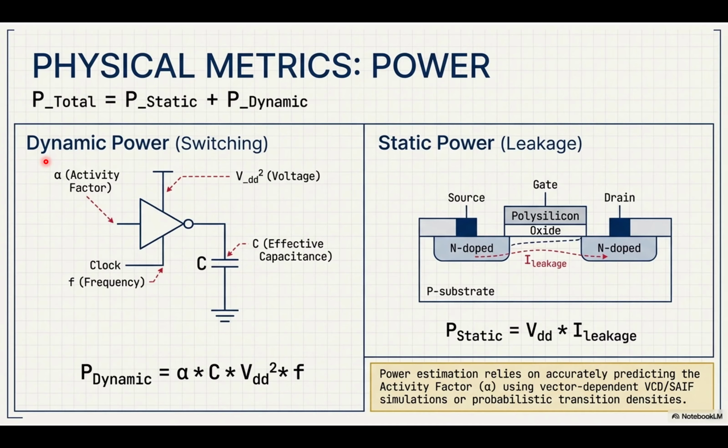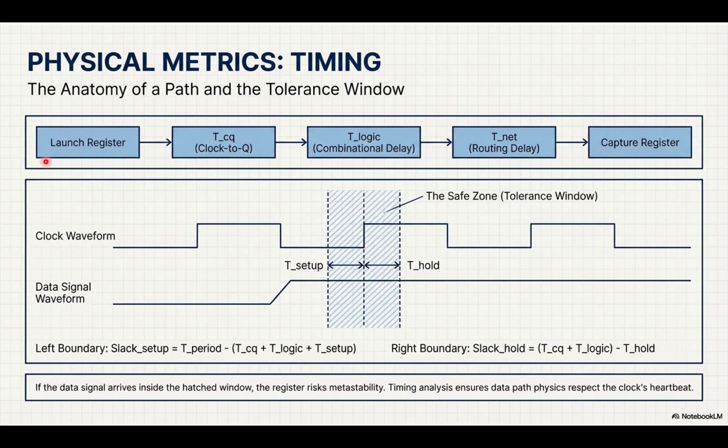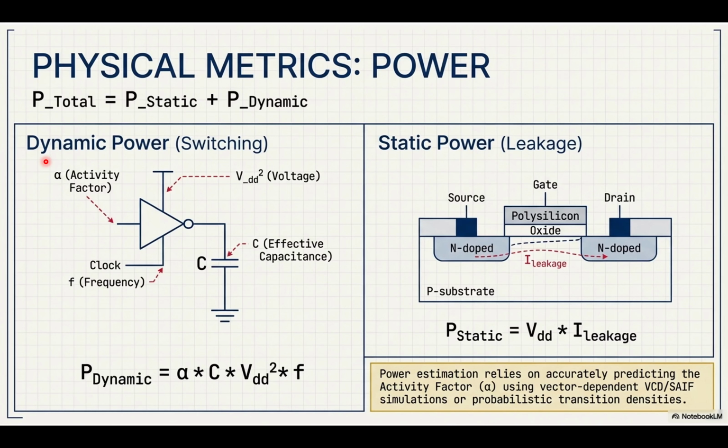So how do the tools actually estimate that dynamic power before the chip is even running? Well, you can use simulation-based techniques. You feed massive files like SPICE or VCD files through a virtual model. It tracks every single net flipping. Very accurate, but I imagine the compute time is brutal. It is, which is why we often use probabilistic-based techniques instead. It relies on static probabilities and transition densities. You get a surprisingly accurate estimate way faster.